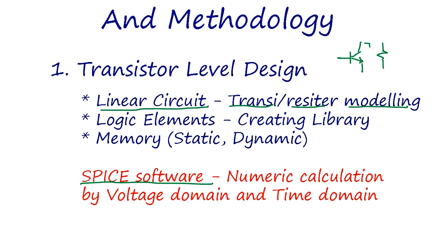Actually, a transistor has many parasitic components associated with it. For example, this base resistor is a resistor associated with the NPN type. This is a P, and this is the emitter N plus, and you have an N type collector, and it has a parasitic resistor here, and the collector embedded N plus for the collector of this bipolar. So there are many parasitic components.